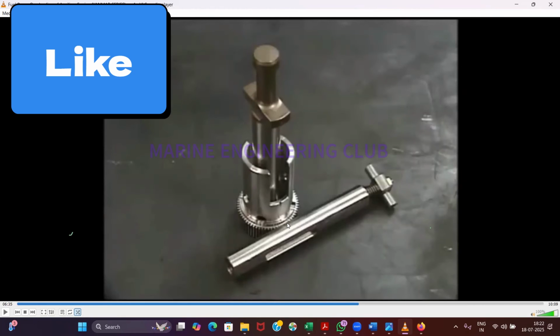So whenever you have done purifier overhaul, do you match the zero marking in it? Yes, yes. Similarly, here we have 3 markings. You should know the parts where the markings are. Plunger foot, there is one marking. Control sleeve, there is one marking. And on my fuel rack, there is one marking. While assembling, all these 3 markings should be aligned. If these 3 markings are aligned, your pump will have zero setting. Is it clear?